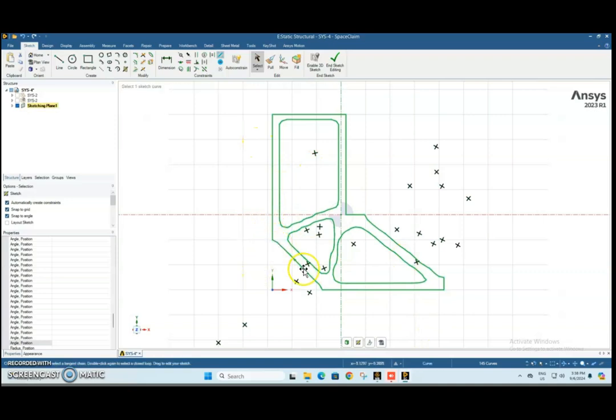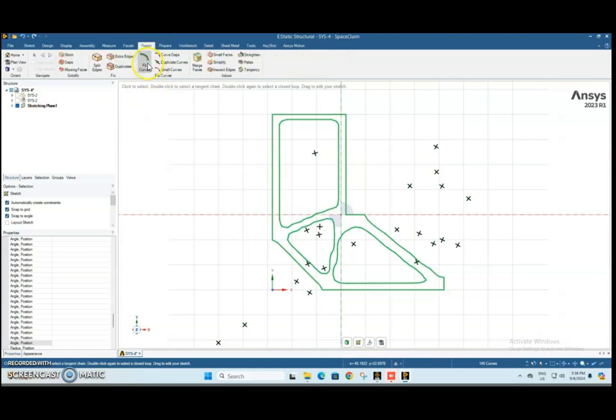Okay, we have to smoothen this and make it a perfect straight line, like this, straight line. This curve, we have to make sure we make it a straight line. So now we have to try to edit this. The first thing we can do is repair this sketch under fit curve. When we click on this fit curve, it will find the curves, all these curves, with points.